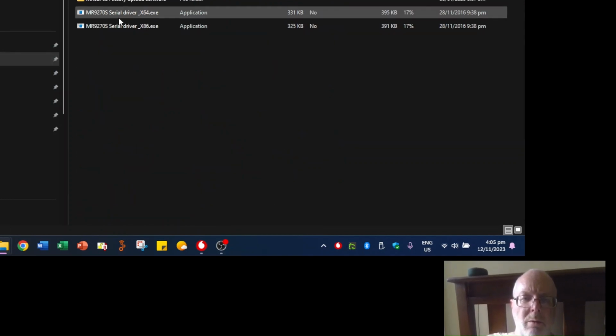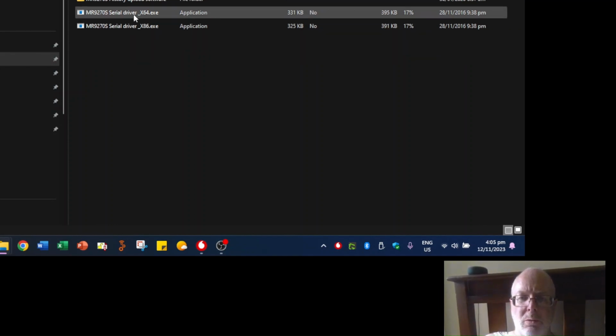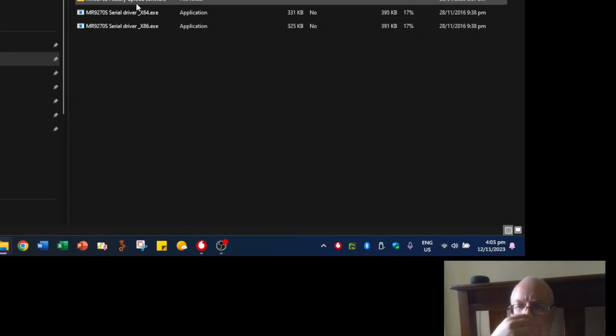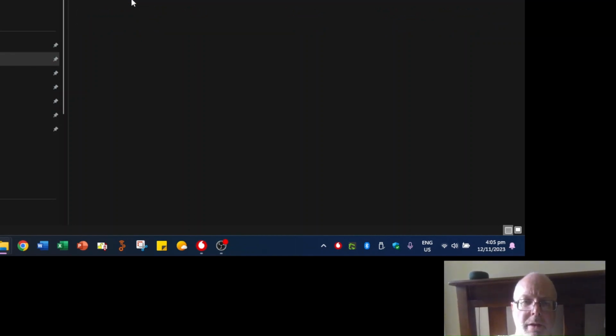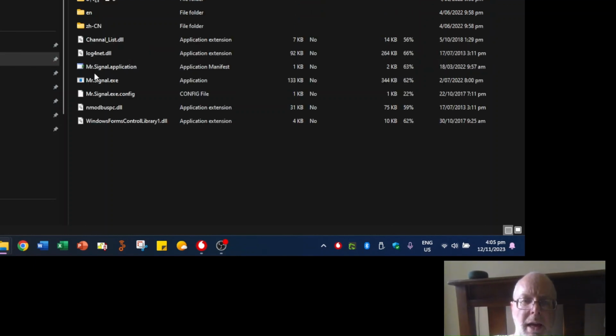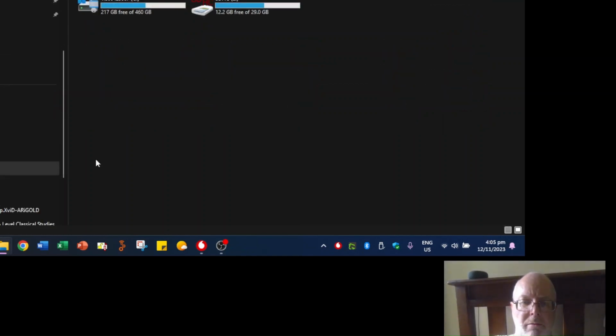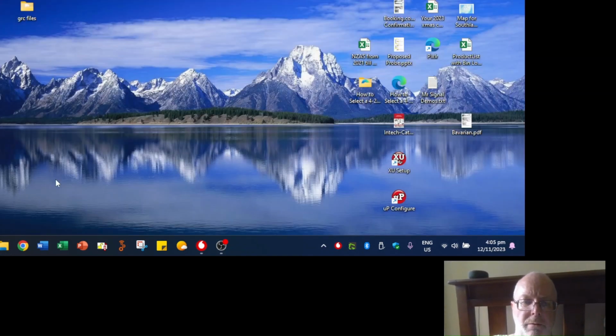As a matter of downloading and unzipping it, within that folder, firstly, we have a driver for 64-bit and a driver for 32-bit. And of course, you install those first. I've done this already, so I won't do it again. And then we have a program within the bin file, and we have Mr. Signal exe. And it's simply a matter of running that program. So follow the setup instructions that I'll show you in a moment. I'll insert them here for setting up the output on the Mr. Signal itself.